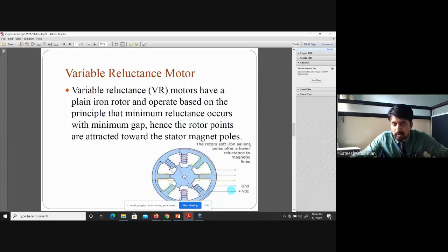Now the stator they have shown with a pink color, blue color, yellow color, green color, like the windings they have shown. These windings they have taken outside, and this will be connected to the driver circuit. The driver circuit will have these many wires, and those wires will be given to this, and that driver circuit will be connected to the DC supply. Basically, as supply goes here, based on the connection here, solid state switches like transistors will be used, and a transistor will be switched on and off accordingly, so that these windings get energized as per our logic.